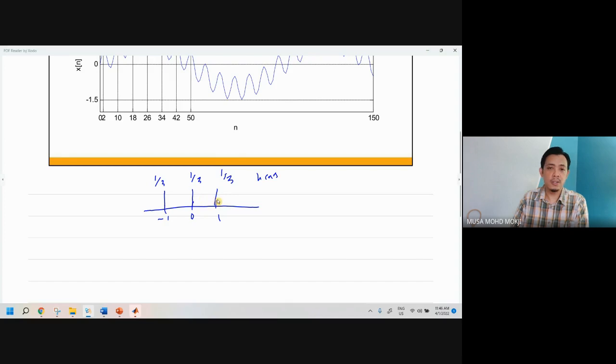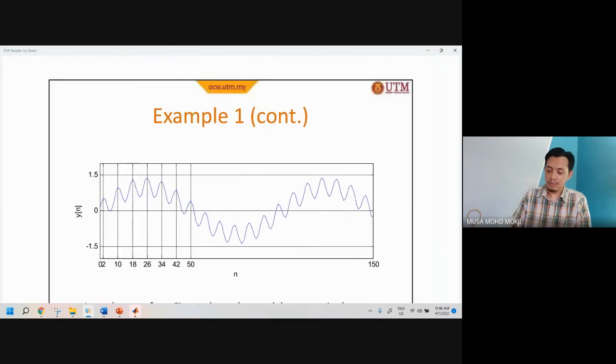When it is not causal, it is difficult to implement, because it will involve a future value. If you are dealing with an online system, you definitely do not know the future value. So this is not a good system because it is not causal. In terms of delay, it is very good because there is no delay at all frequencies. But it is not causal.